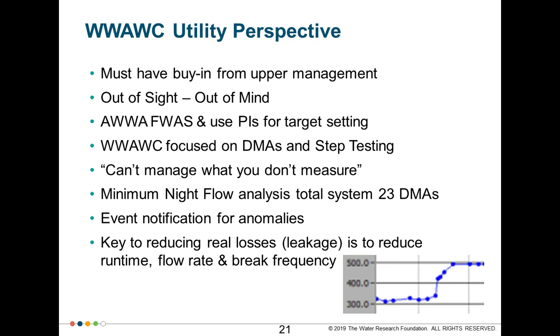So from a utility perspective, just share a couple points. First, you must have buy-in from upper management. Well, I manage a smaller utility, so that's me. I am upper management, and obviously I've bought into it. Just want to share, though, as a utility manager, many things are out of sight, out of mind. You know, the tanks are full, none of the customers are complaining, everything's moving along. But remember, we're dealing with buried infrastructure. It's not like potholes in a road, so we don't know what's going on underground. That's 3 foot or more buried infrastructure. So you've got to use the tools, the AWWA Free Water Audit Software, and use those performance indicators for target setting.